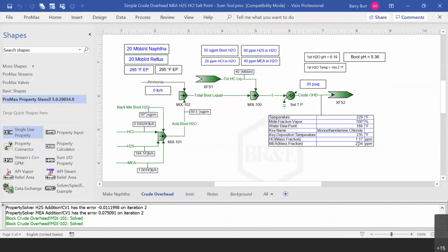Oh, simulate corrosion rate in the tower. Well, to simulate corrosion rate of this form, you would have to be able to predict that there is a free water phase forming on an equilibrium stage somewhere in the tower. And normally we'll have these columns set as vapor-liquid-liquid equilibrium columns, but usually we only set the condenser stage as being one that could have three phases.